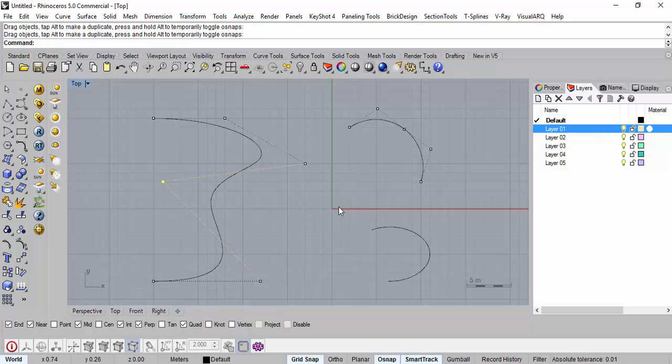Is this clear? Now most of the curved geometries that you can build in Rhino come from curves. You don't have standard solid objects that we can work from, except for the primitives. Which are the curved objects in primitives? You have a sphere or a cylinder, right? There's nothing else. And there is a very limited way you will be able to edit even those. You won't be able to create very complex or out of the box kind of shapes from those original primitive shapes. But here you can create any shapes, but you have to begin with a Bezier spline like this.